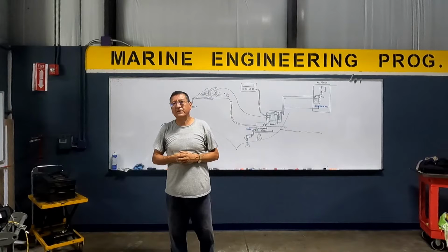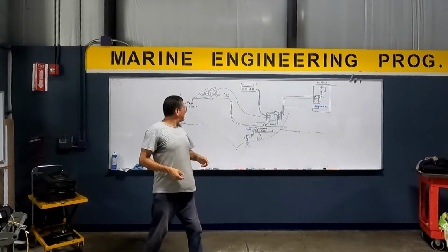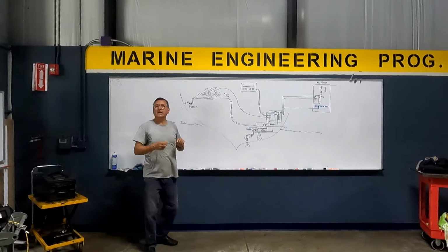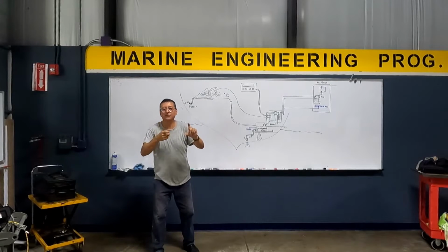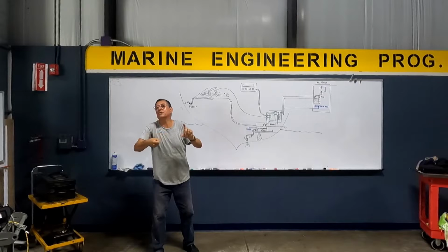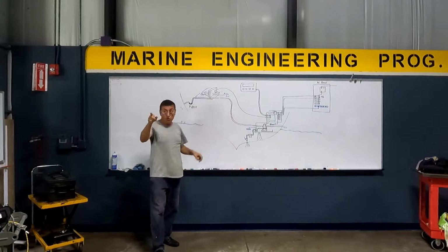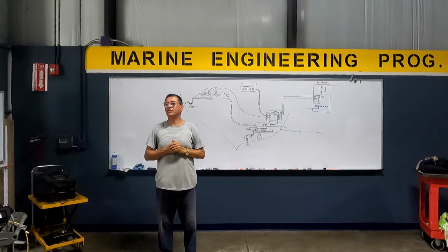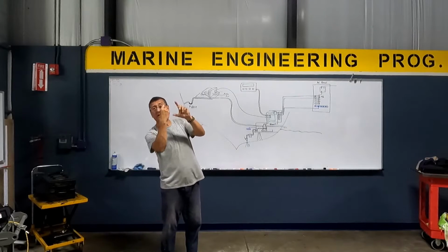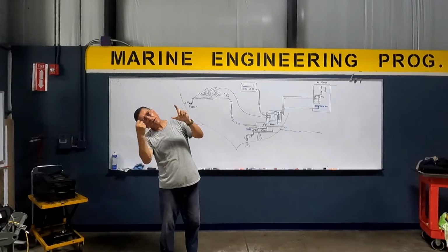It's clear, my friend? Periodically, you need to remove the filter, apply a special spray to clean the coil, the radiator, and spray water at high pressure in this coil, in your boat and in your home. Once per year, try to do that service in your home. Spray the cleaner and water at pressure.